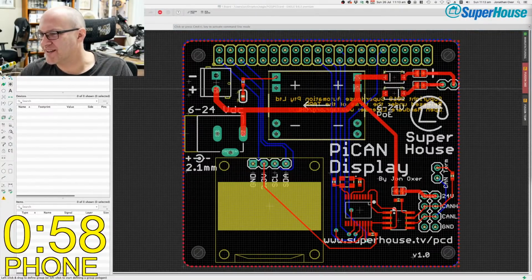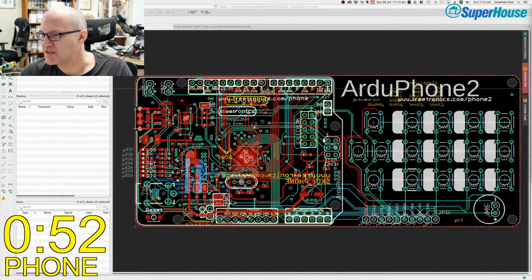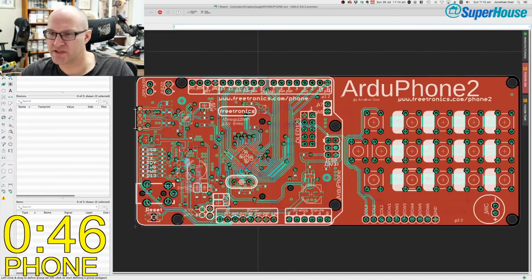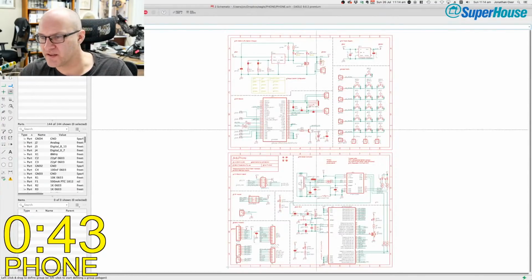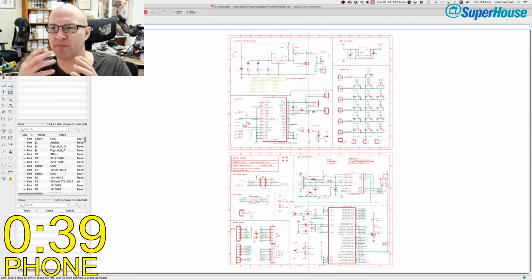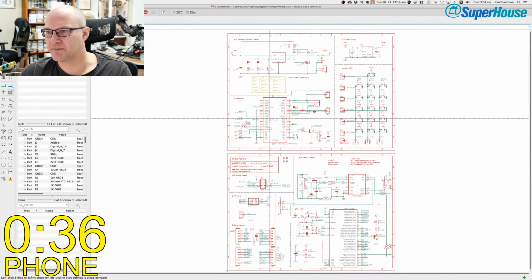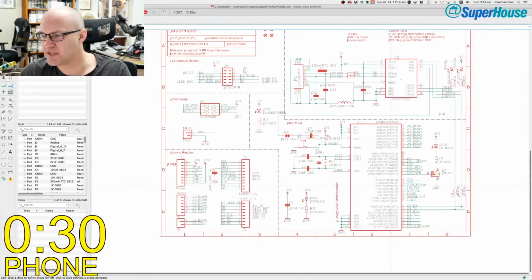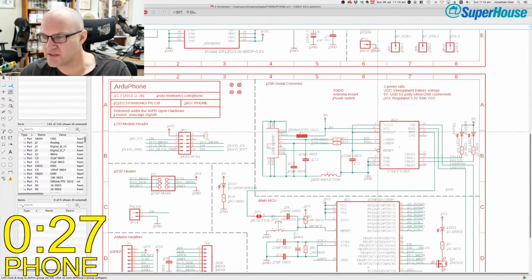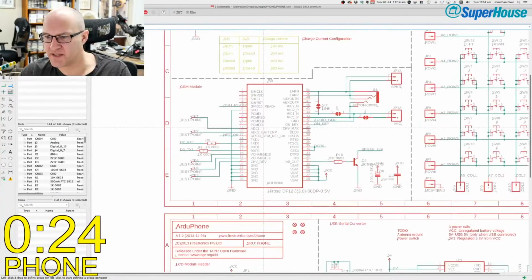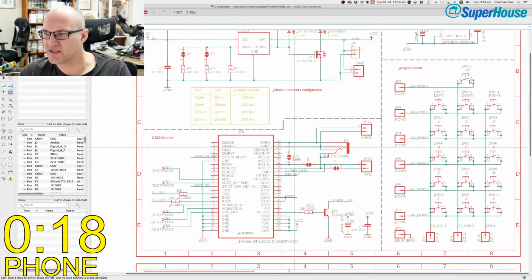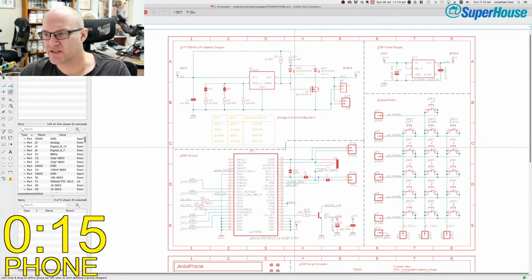Phone. Oh, I love this project. I'm so sad that this kind of doesn't really even exist anymore. This is an Arduino compatible mobile phone, and this was done a few years ago for Open Hardware MiniConf as a way of showing people how mobile phones work, like what the major components are within them. So there is the main processor here, which is an ATmega 1284P, and there is a USB interface, but up here there is a GSM module. Was it the ADH8066, which is obsolete now because I think it's like a 2G module.